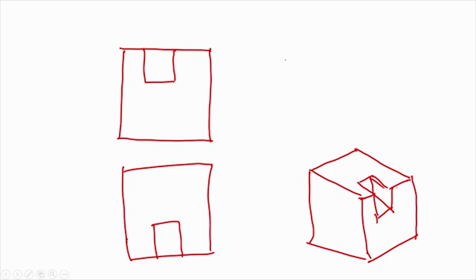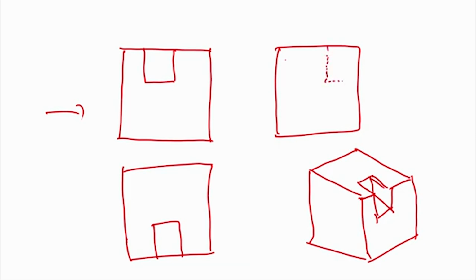In this, it is a solid in which a small portion is removed. Even here, there is still a small chance of ambiguity. So, conventions have been developed which will show clearly what it is. If I now draw another view of it from this side, just as before, there is no way of showing it, because this edge is not visible. So, it has come to us saying you show these edges in a dotted line. Now, if I show this dotted line, you can easily imagine this object, and more than anything the dimensioning is very easy. No dimension can be repeated, no dimension need be interpreted.